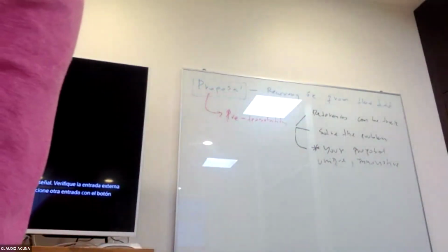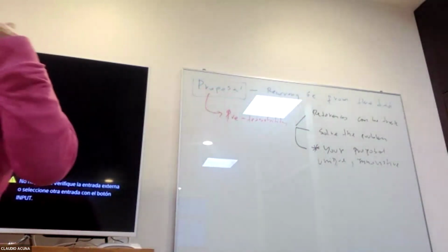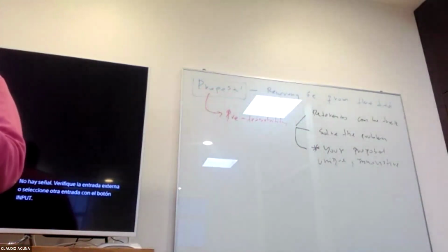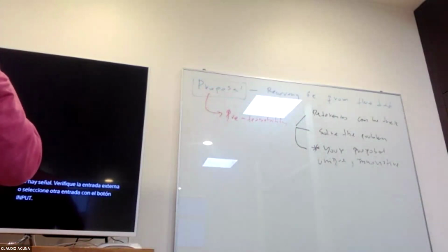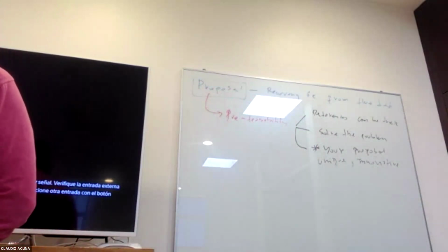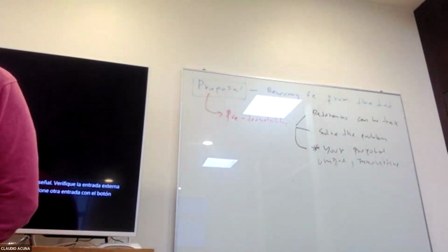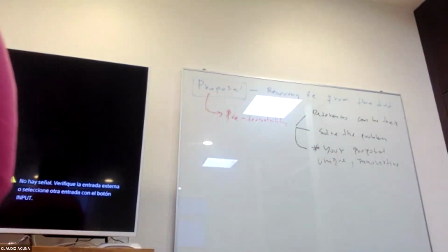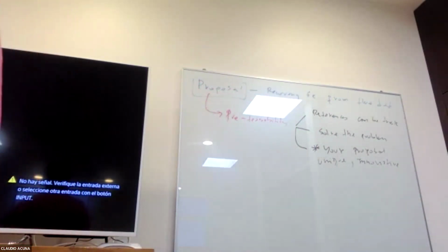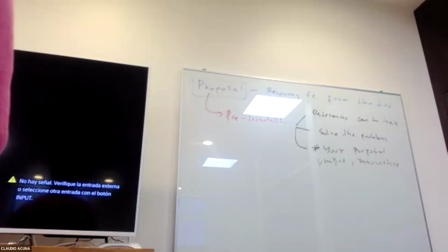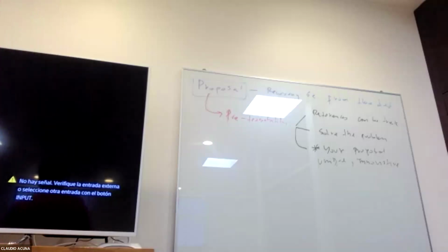When we're talking about fine particles, we have a solid-liquid reactor. What does it mean in practical terms for the operating conditions of this reactor, and how does it impact the economic evaluation? When you're working with agitation and fine particles, and fine particles under shear, the limiting factor in the operating condition will be mixing. But as a consequence, for the flow rate, you need to work with a more dilute pulp.